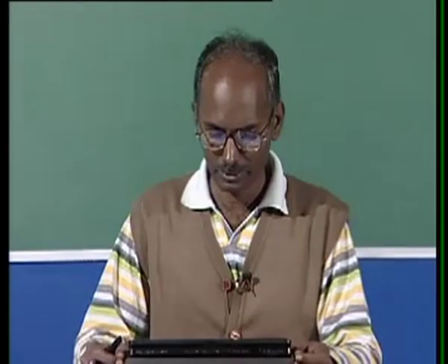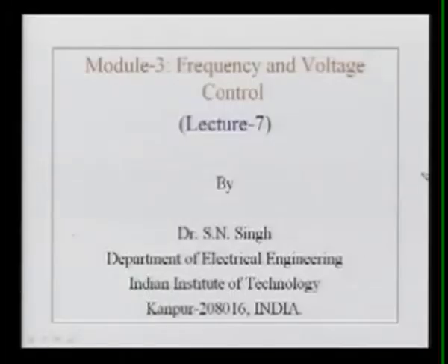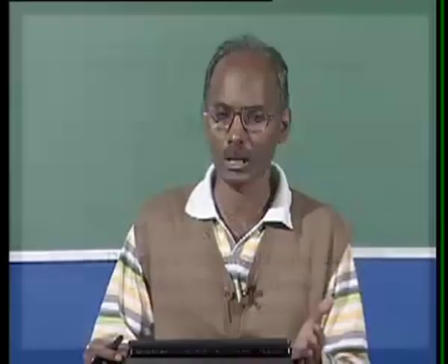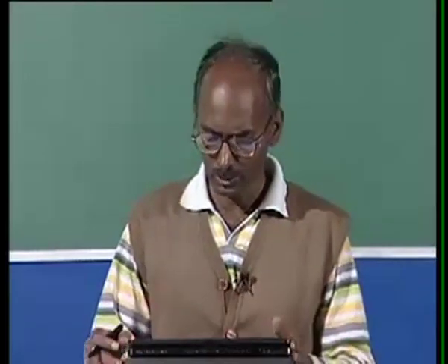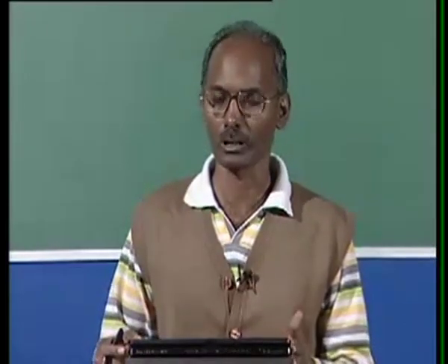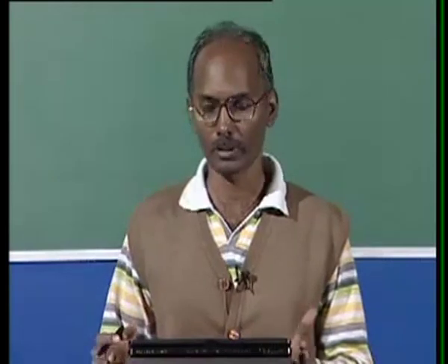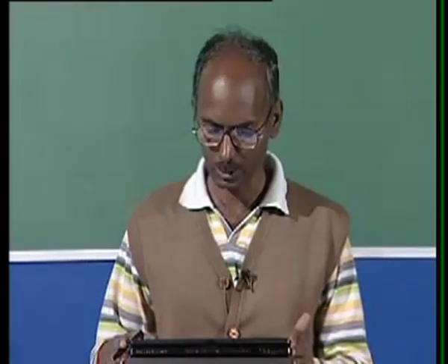Welcome to lecture number 7 of module 3. In this lecture onwards, I will be discussing the voltage control. In the previous lectures, 1 to 6, we saw the modeling and how the frequency of the system will be controlled. The voltage control is basically related to the reactive power control, meaning the reactive power and the voltage are both related to each other.